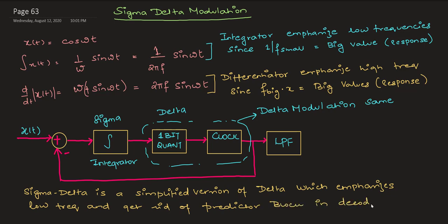We have seen the first order predictor differential quantizer. We have seen a few examples of those quantizers, which are delta modulation and sigma delta modulation. Sigma delta modulation is much more efficient because it uses an LPF on the encoder side and also on the decoder side, which can be synced together to get the best reconstruction results.